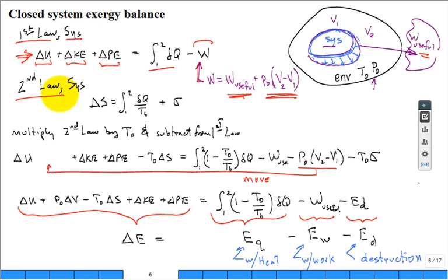You write it for the system undergoing a process from initial state 1 to final state 2. So what is this? Change in entropy. What is this? The entropy transfer across T_b. Isn't that T_b right there? It's hard to see, but what does that B on that temperature mean? The boundary temperature. Right? That boundary temperature could be constant, that makes the integral easier, or it could be variable, which makes the integral very hard. All right. But we're going to sum up all of the heat transfers divided by the instantaneous boundary temperature and sum them all up for the process.